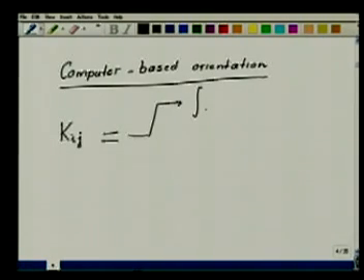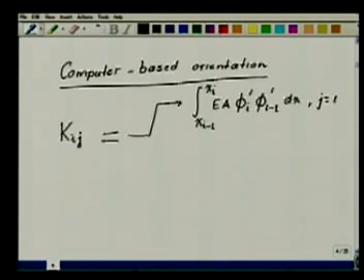For j equal to I minus 1, I will have in the element x I minus 1 to x I, if you remember, it will be equal to integral EA phi I prime phi I minus 1 prime dx for j is equal to I minus 1. That is only in the element I minus 1, this part is non-zero, everywhere else it is 0.